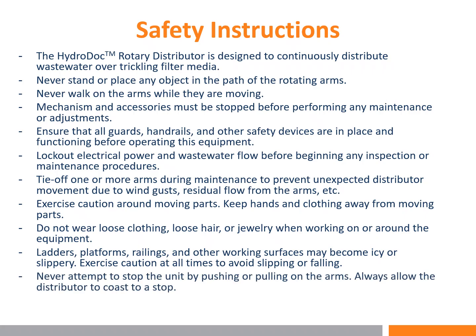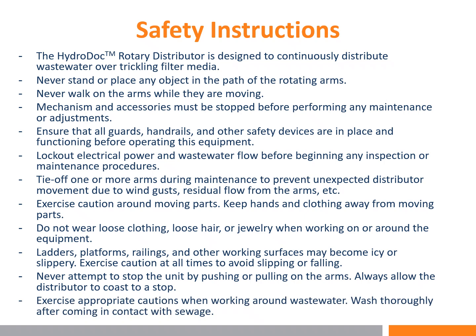Never attempt to stop the unit by pushing or pulling on the arms. Always allow the distributor to coast to a stop. Exercise appropriate cautions when working around wastewater. Wash thoroughly after coming in contact with sewage.